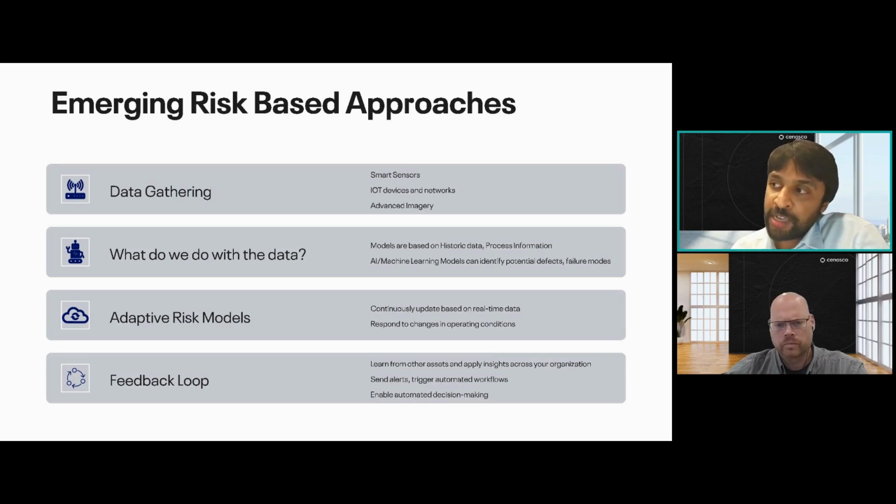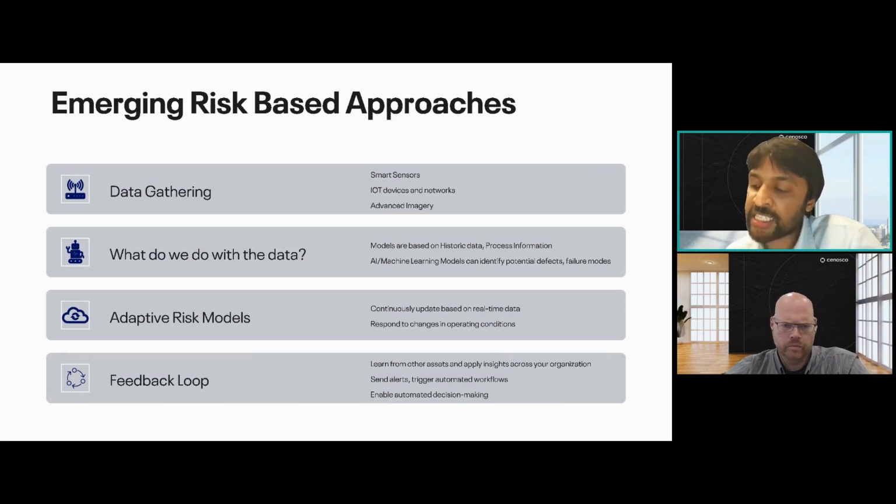And then based on all the scan data, we can process it through AI ML models and identify locations where external corrosion is typically present. Most likely a screening tool. External corrosion is one, damage to insulation could be another as well. So instead of performing external visual inspections on a regular basis at specific parts of your asset, you're doing an extensive external assessment across your entire asset in one go.